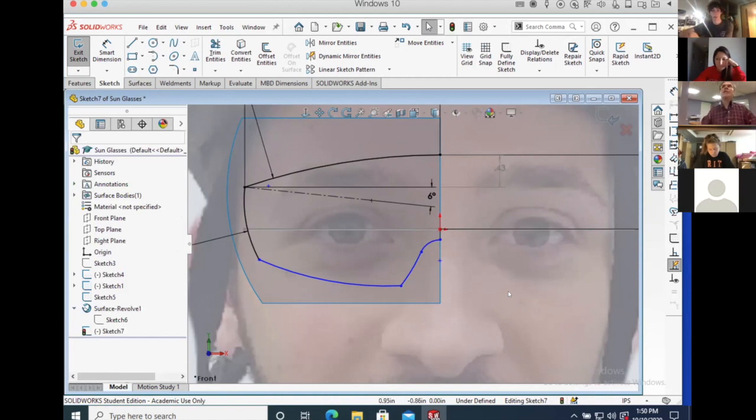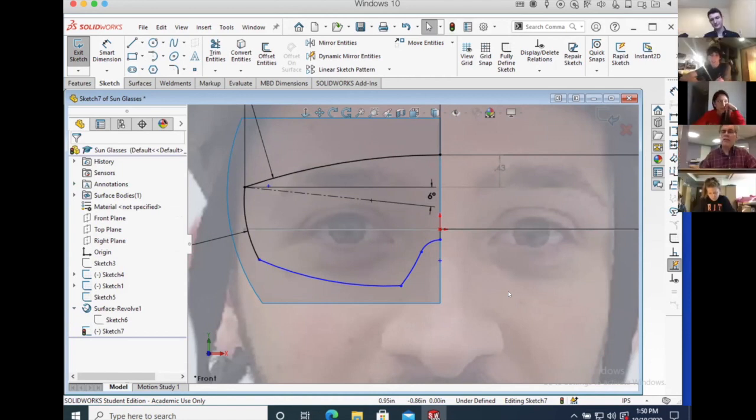Everybody loves splines because they're so intuitive and you just lay them down. But it's like designing something precise with a noodle. Only use a spline if you really need a continuously variable curve and an ellipse won't do it for you. They're easy to put down the first time, and then they're hard to work with after that.